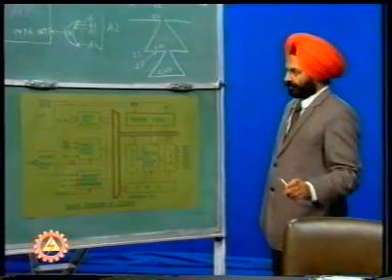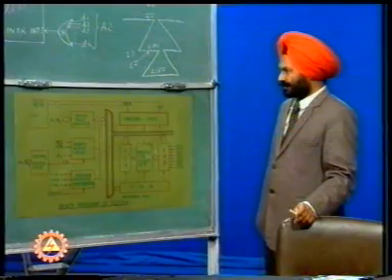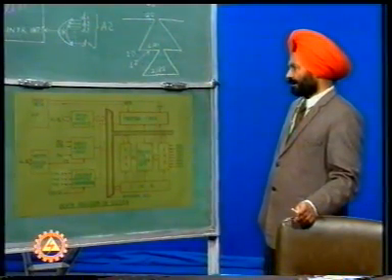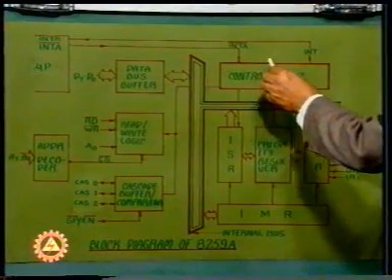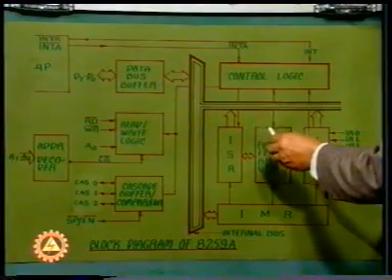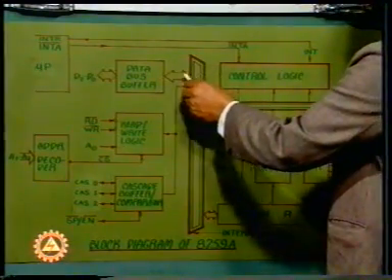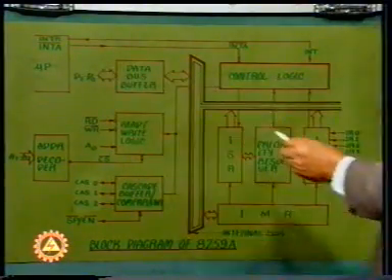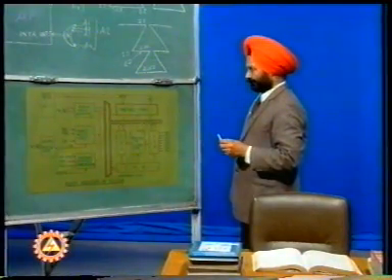On receiving the operation code of the call instruction, the microprocessor sends two subsequent acknowledgements to the controller, thereby asking for the address vector of the interrupt service routine. The controller responds by sending the lower and higher byte of the address to the microprocessor, and correspondingly the microprocessor then branches to the required interrupt service routine, servicing the interrupt.